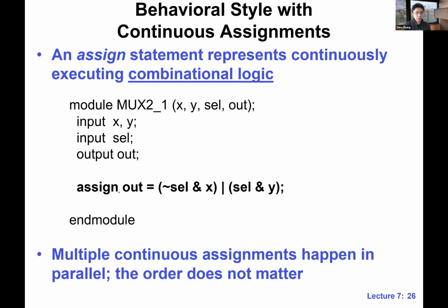And this is something that I just showed you, right? So when we describe a simple circuit like this, I recommend you use assign. It's called continuous assignment, but this is only useful for specifying combinational logic, and also only useful when you have a short expression like this, like a mux. And you may have many assign, right? You can actually do many other assign, like this, R1, blah, blah, and we can do R2, right?